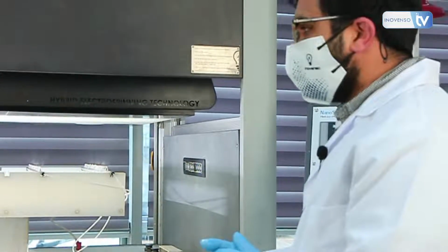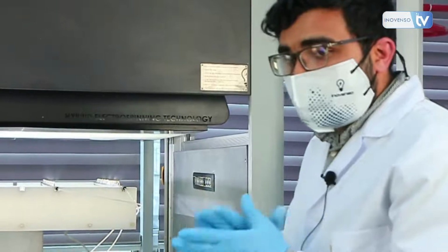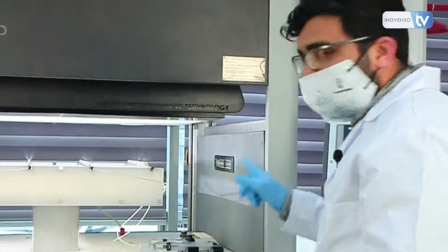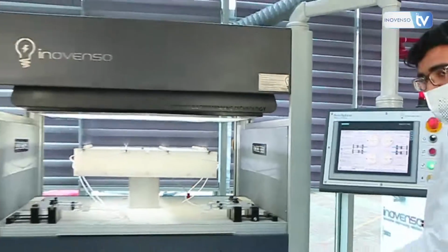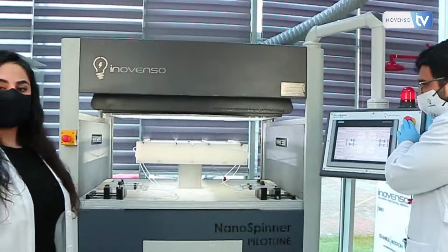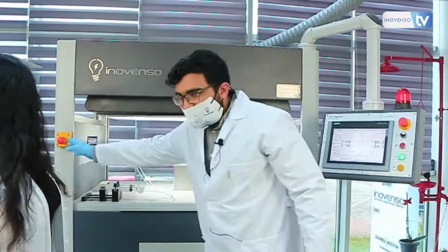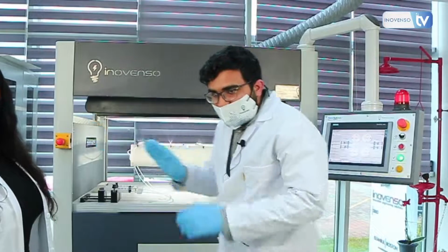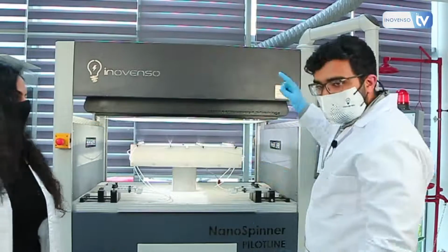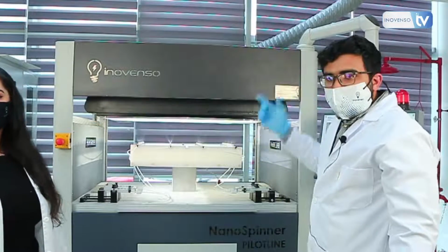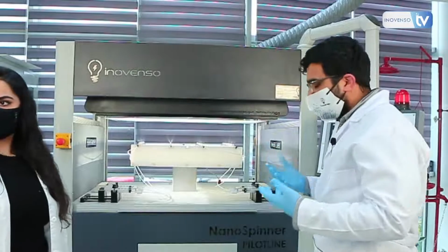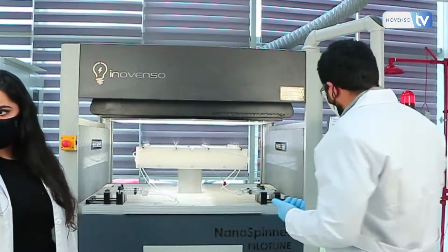Another safety feature is that in cases of emergency where you need to cut the high voltage supply, we have three different buttons. One is on the control panel, which is the emergency stop button. The other is the emergency stop button here. If you press that, the machine will close. And the last one is at the back of the machine. Since the machine itself is huge, we have three different buttons for it.